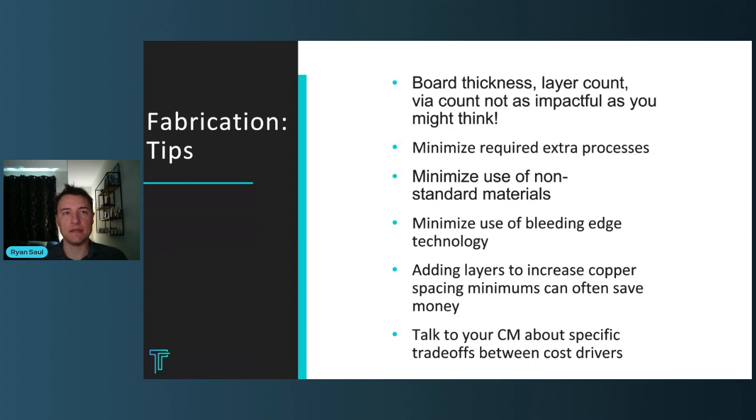Okay. Next area is, again, sort of jumping back to the top a little bit. Adding layers is not bad. I highly recommend adding layers. If you don't have enough real estate in your design to get all your signals routed, add a couple layers. You will add to your cost, but it won't add to your cost as much as pushing copper spacing, for example, would add to cost. So I would say go for it.